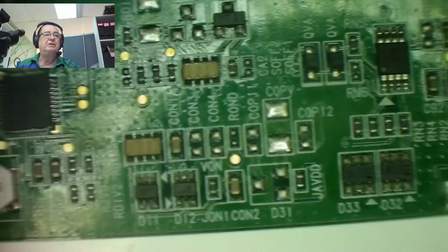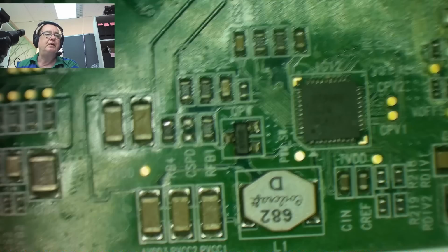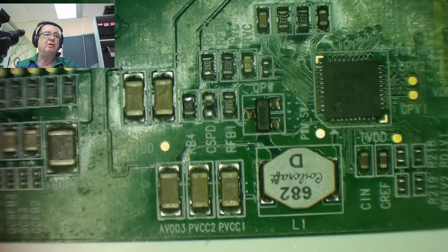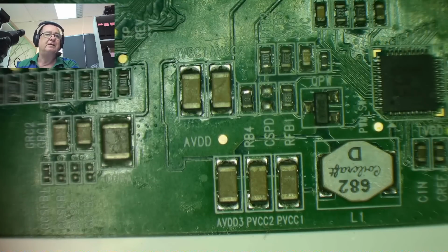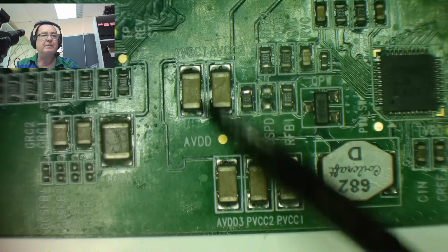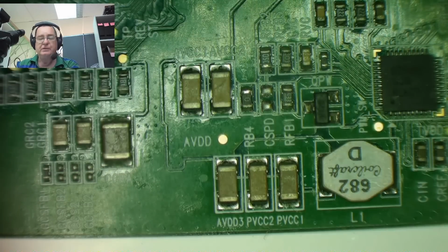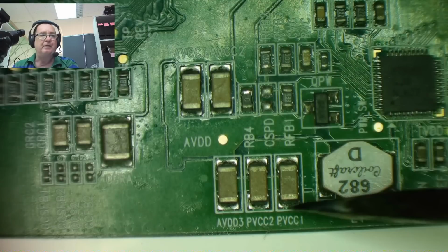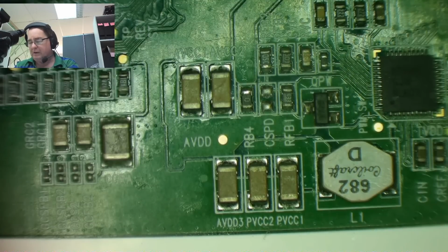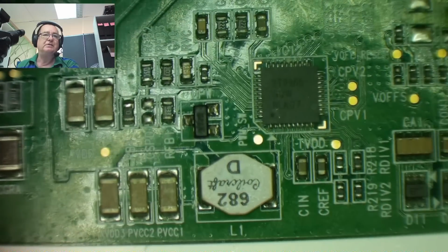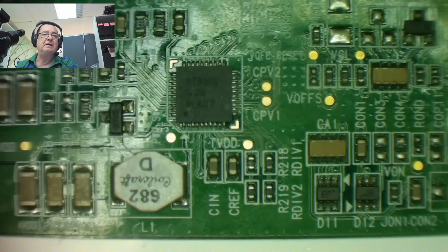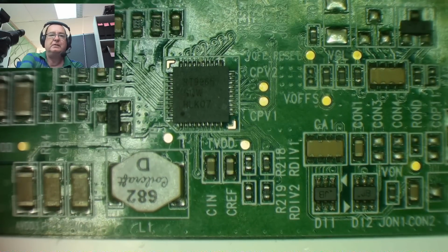So I think capacitors are a good place to look, because if you've got a voltage rail, the chances are you'll find that voltage on capacitors. There's some bigger capacitors, and this is AVDD. So I'm going to again take a photograph of the screen and just check all the voltages on these capacitors on each panel and see if I can see any difference. Okay, so I'll do that now, and then I'll let you know what I find.